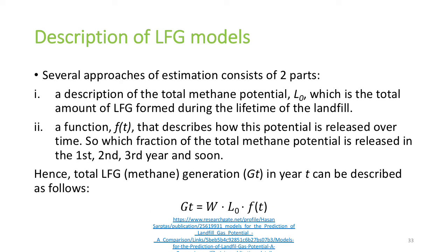Now we will look at the description of LFG models. Basically, all the models have two parts for the estimation of LFG. First is the description of the total methane potential, that is L0, which is the total amount of LFG formed during the lifetime of the landfill. And the second is the function F(t) that describes how this potential is released over time. So, which fraction of the total methane potential is released in the first, second, third year, and so on. Hence, the total LFG generation G(t) in year t can be described as G(t) = W × L0 × F(t).